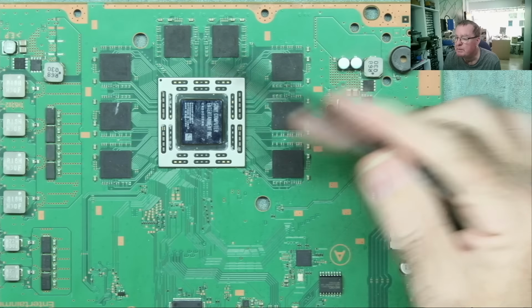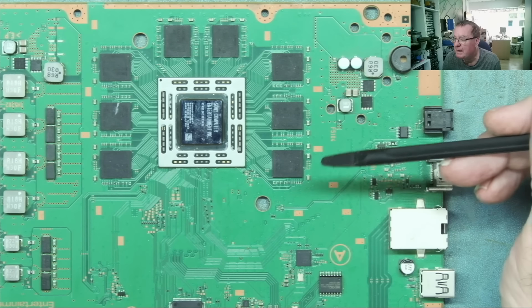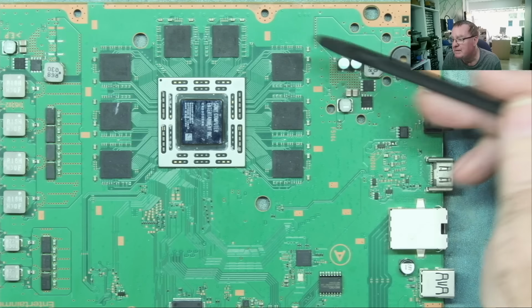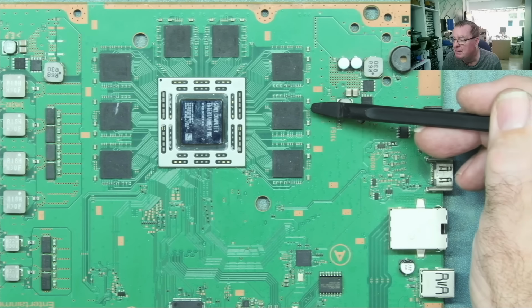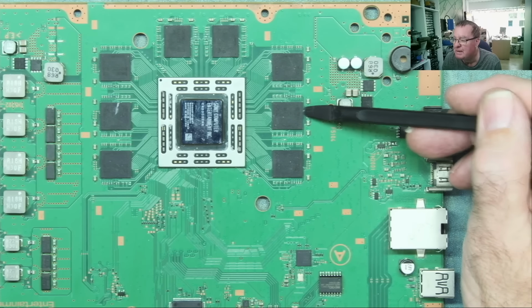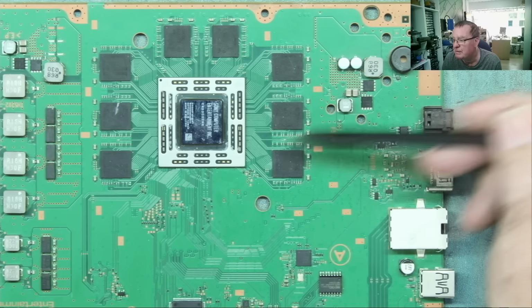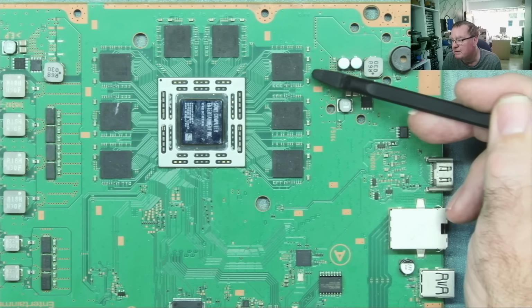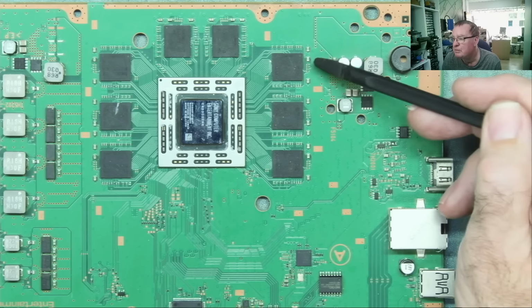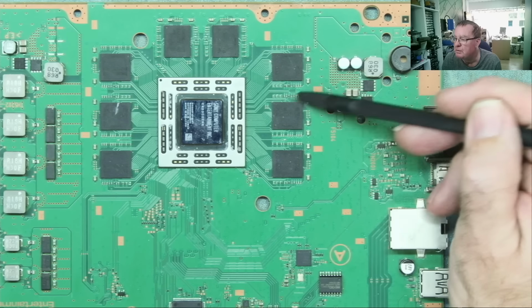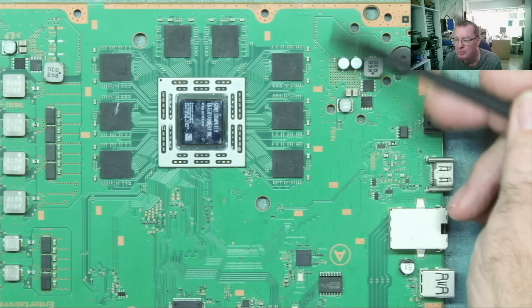Like anything else with BGA rework, it requires the right equipment and the skills. And again, with this reflow where you're just tapping the chip gently after you've melted the solder, the best way to practice at first on the scrap board like this, if you see the thing springing back, you'll get a feel for it, how far you can hit it, because if you move it too far, you'll end up with shorts on the balls. You have to reball it anyway.